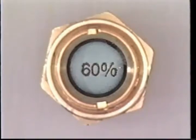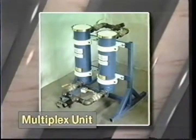Changeover is quick and easy. The operator shuts off the saturated desiccant unit and turns on the unit with fresh desiccant. Within a few minutes, the moisture indicator returns to its blue color, indicating dry air is flowing. Change out of the saturated desiccant can be accomplished on a routine maintenance call, eliminating a costly shutdown.